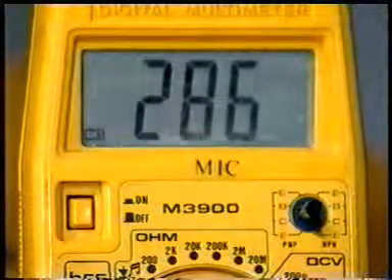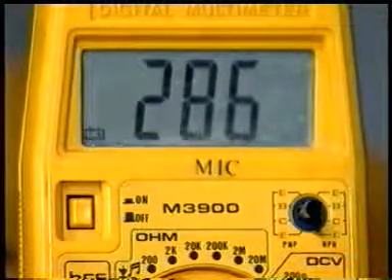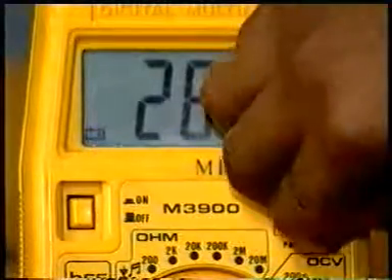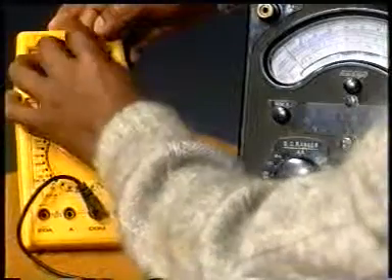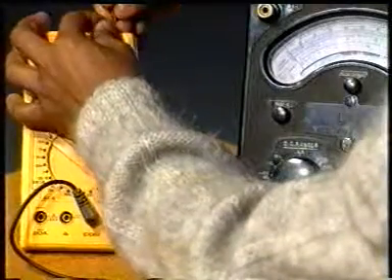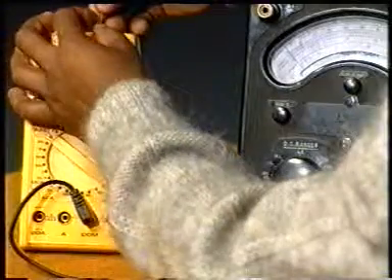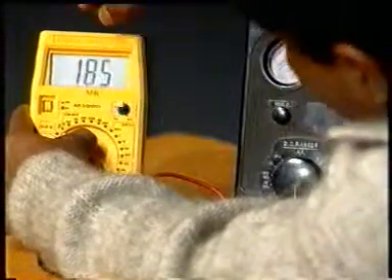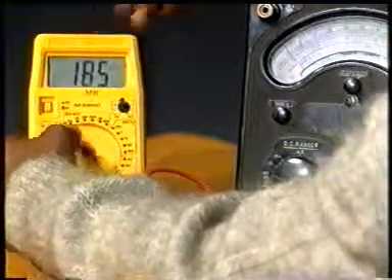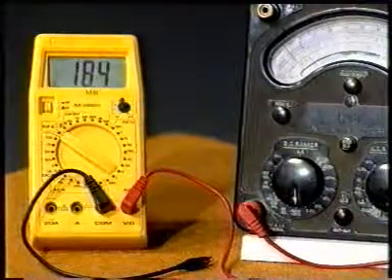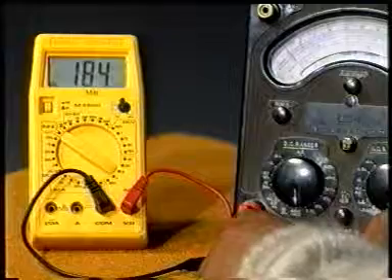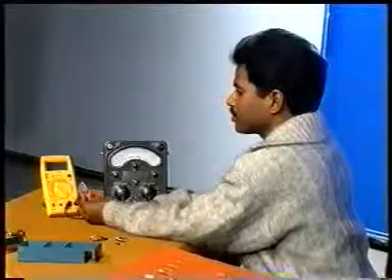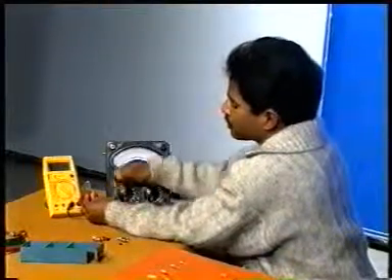So this is also a check by which you can find out whether the terminals are correct or not, and which type of transistor it is. Change the transistor please. Yes. Again it is showing gain. If it is wrongly connected, it would not have shown this gain. So this way also you can find out which type of transistor it is and which are the terminals, emitter, base and collector. Now the same test can be done for a power transistor also.